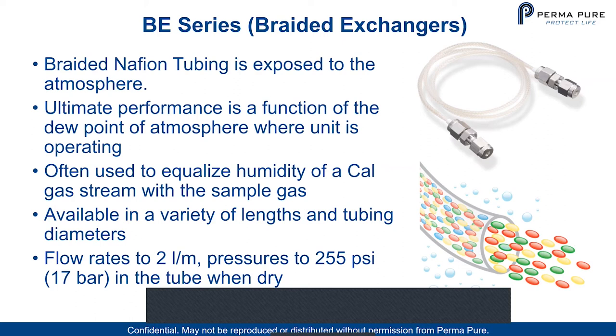We can attach a metal connector, a typical compression style connector, and we have a very strong strain relief. That means we can pull that connector, and the mechanical strength is from the encapsulation, or the enveloping, of that polypropylene around the netting that has been weaved around the tube.